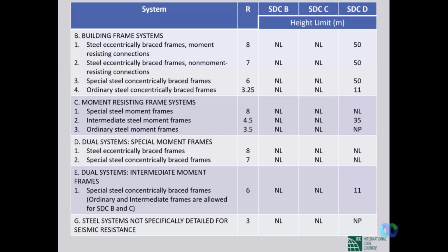And even for the ordinary moment frames or braced frames, we'll have to comply with section 1020, that is seismic provisions. We'll discuss tomorrow how much of that is related to ordinary moment frames and how much we have to follow for special moment frames. But as of now, you can understand, even to design ordinary steel moment frames, we have to comply with section 1020, which are seismic provisions.